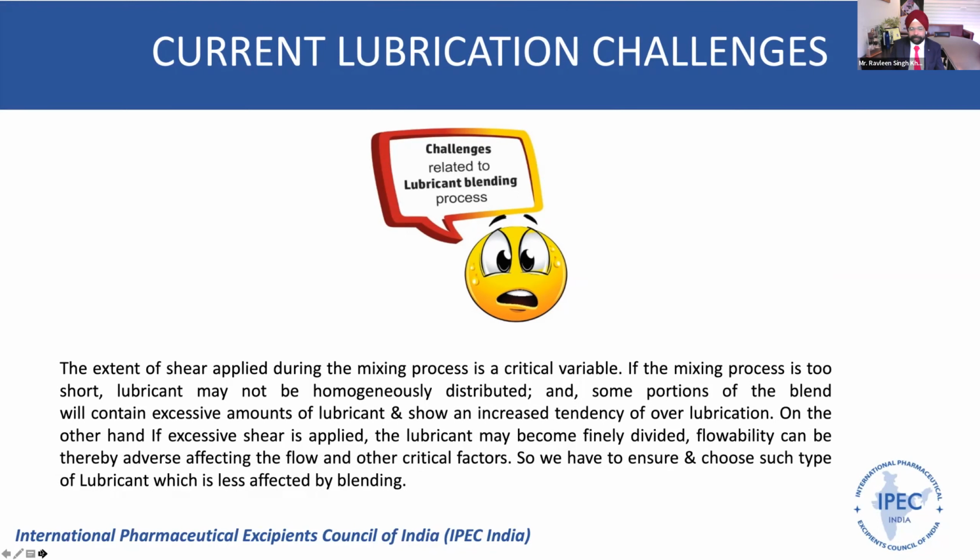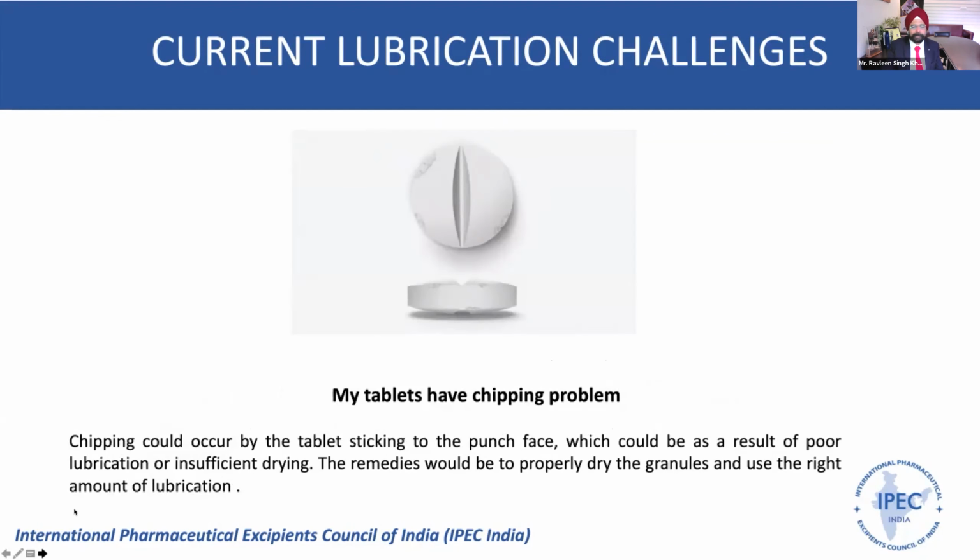And believe me, friends, there are grades of different lubricants which will not have effect of blending time on them, and even the blending ratio or even the blending schedule, like how you do the blending, what you add first, will have no impact. So such lubricants are available. But if the quality is not good, then you're going to have this challenge. Then the chipping problem. Again, the tablet will be chipped off. It will stick to the punch face, and the proper lubrication can avoid this.